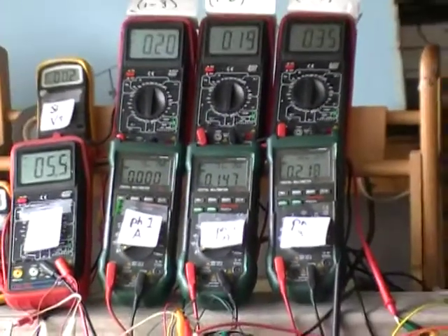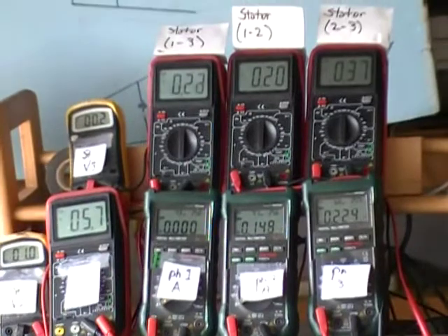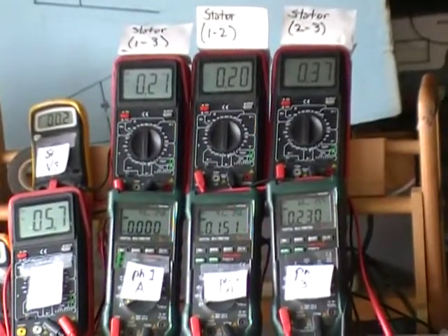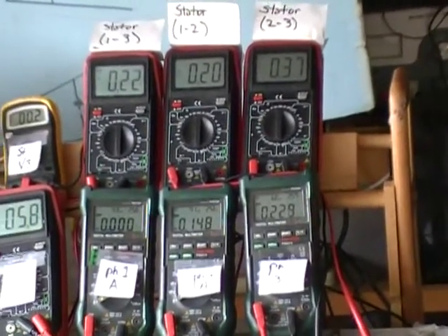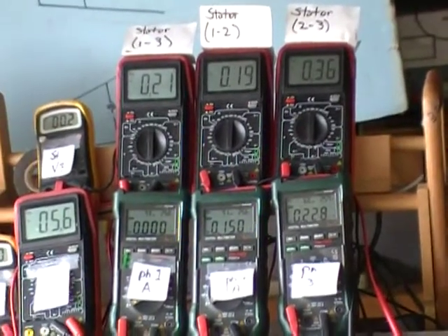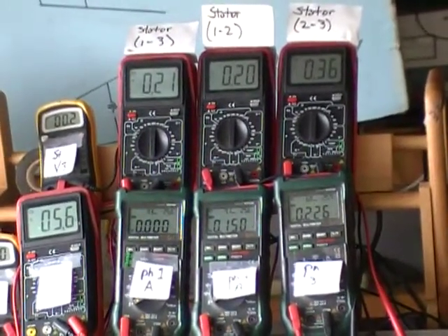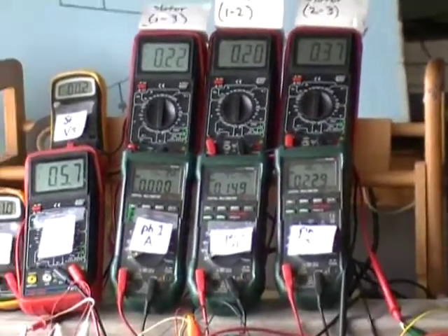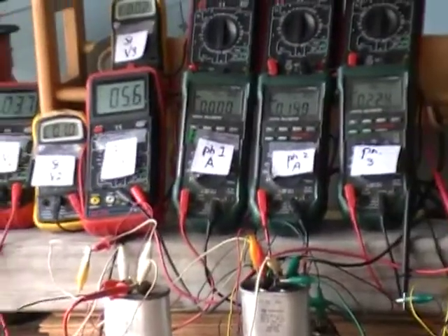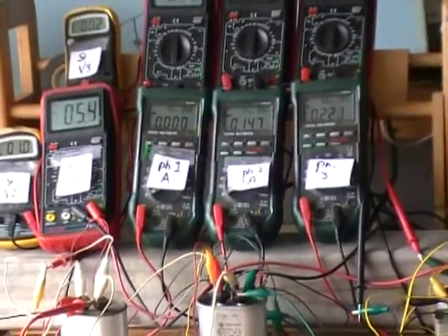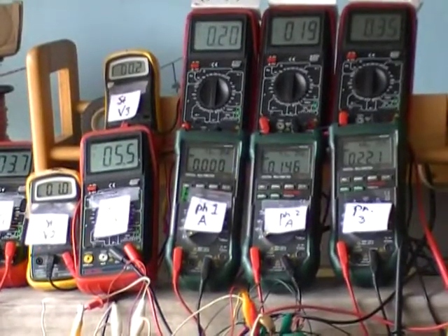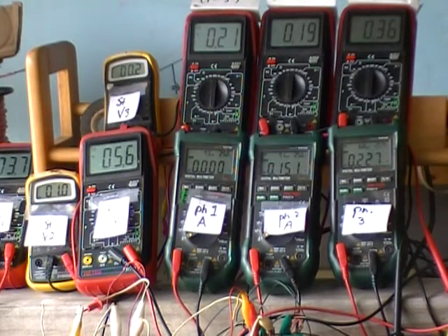Then we've showed the relationship between 2 and 3 on our stator amperages. They seem to be fairly balanced. Well, not really balanced, but could be a lot worse. We're only employing 2 phases. Now we notice that in this situation we have 1.2 volts on the empty phase, number 1. We have 1 volt on phase 2, and we only have 0.2 volts on phase 3. So what we're going to do now is disconnect phase 3.